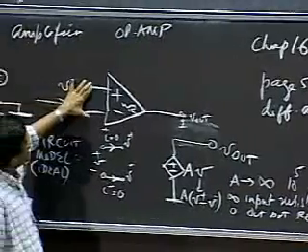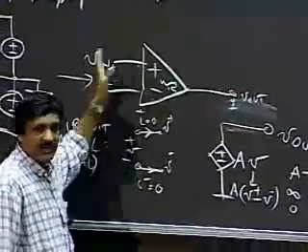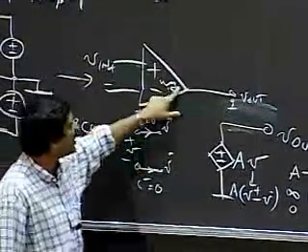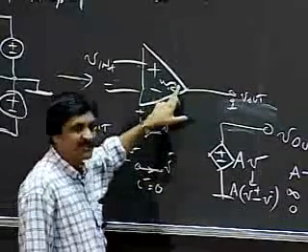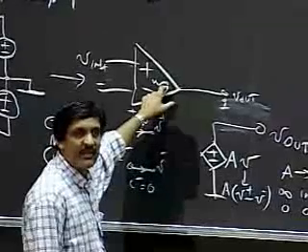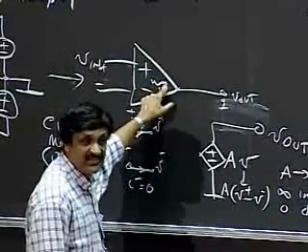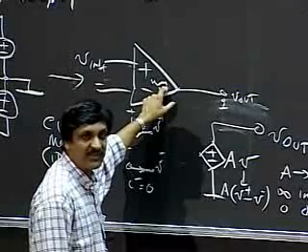So that input stage is what's inside the op-amp. It's got a bunch of other circuitry like level shifters and so on. And at the output, it's got a buffer, something reminiscent of the source follower circuit that you learned about in recitations, a solved example in the course notes, and in your homework as well.